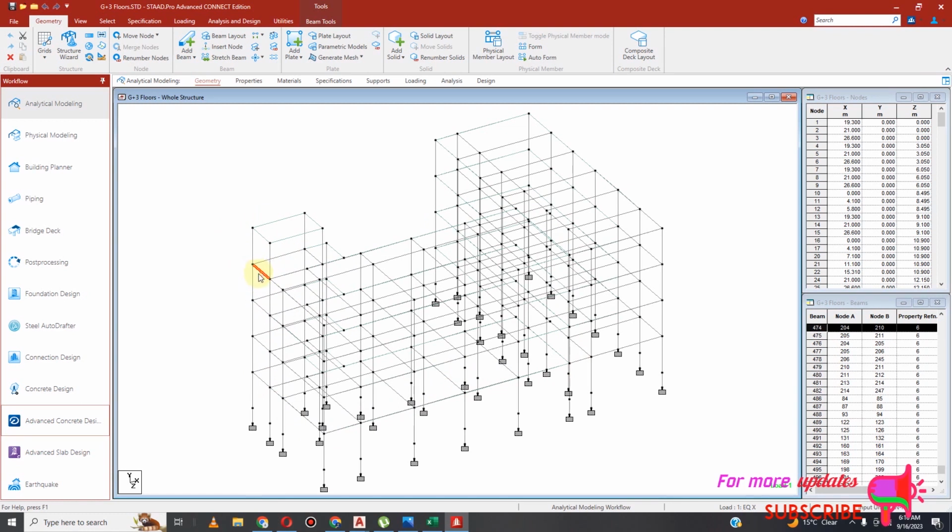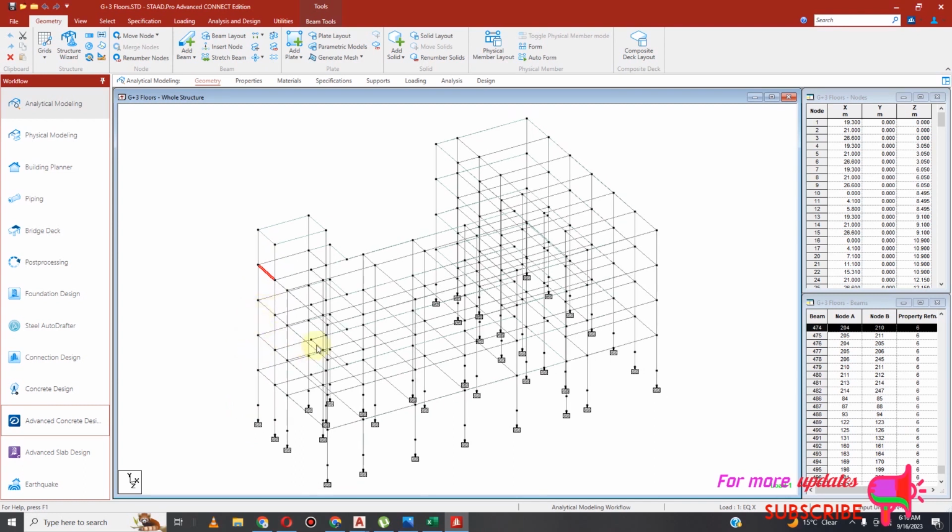But remember to add here a load of 11, 11, 11, and then to the, that is to the 22, 22 for the 22 kilonewtons per meter for the weight of the slab of the stairs. Okay, and for the roof you can add 11 because now remember stairs the weight looks like that. So this one will be sharing, but this one will be holding the entire weight. So it will be 22, 22.